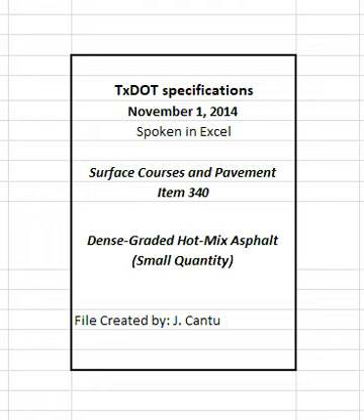2.3 Baghouse fines. Fines collected by the baghouse or other dust collecting equipment may be reintroduced into the mixing drum. 2.4 Asphalt binder. Furnish the type and grade of performance graded, PG, asphalt specified on the plans. 2.5 TAC code. Furnish CSS1H, SS1H, or a PG binder with a minimum high temperature grade of PG 58 for TAC code binder in accordance with item 300, asphalts, oils, and emulsions.